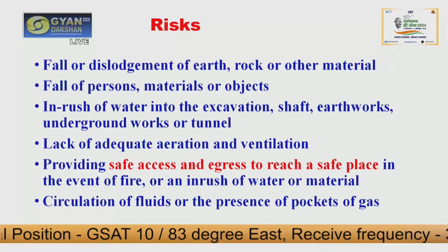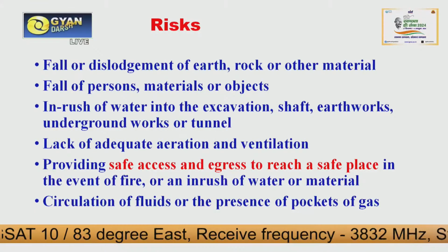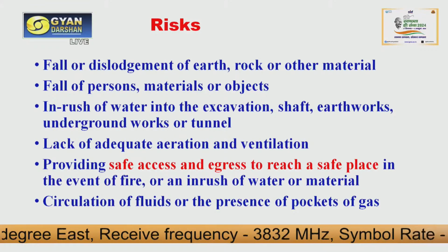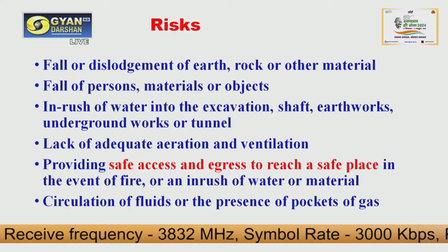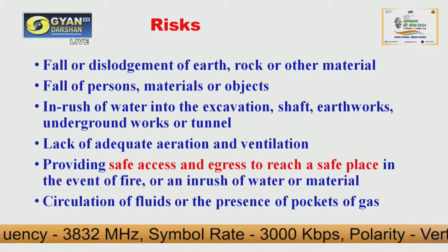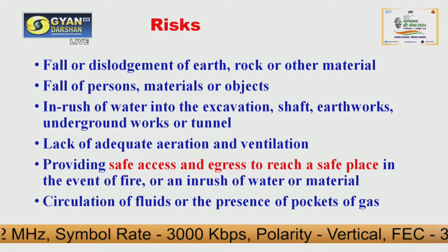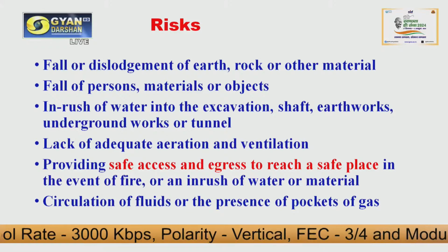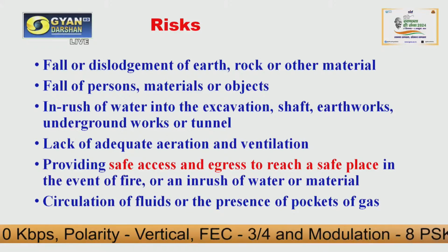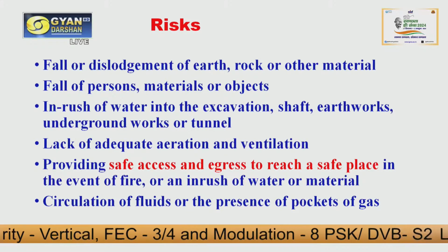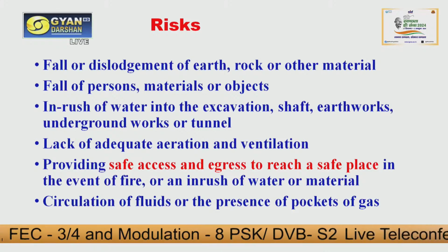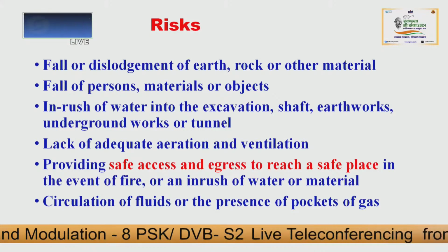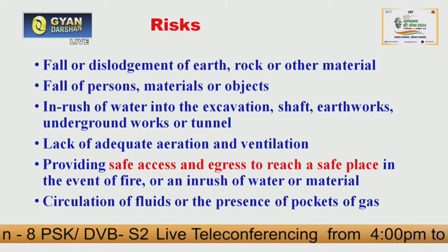Then what are the risks associated with this underground construction? There may be a fall or dislodgement of earth, rock or other materials which may hit the workers. Persons may fall, or objects or tools which the workers are carrying may slip and fall and hit another worker.